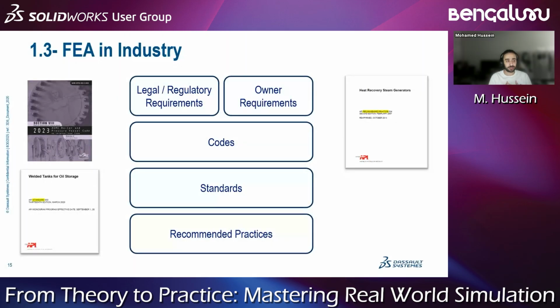So at the current time, if any of you perform this analysis, you have to check first if it's accepted by the code, if the code is allowing you to use FEA. That was the first mistake that I made, and I learned that I have to follow the requirements first, and then check if the code allows the use of FEA and what the criteria are for the person who is doing FEA.